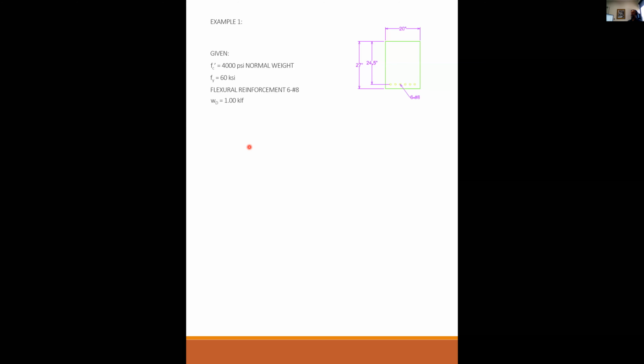We don't need to add that to it. Okay, so that's my story, and I'm sticking to it. So if I do not say something like does not include self-weight, then if all you're given is the dead load, you may consider that the self-weight of the beam is already wrapped up in that package.